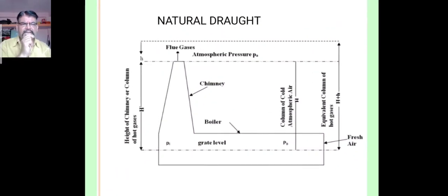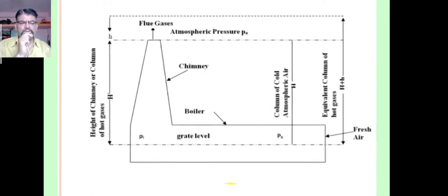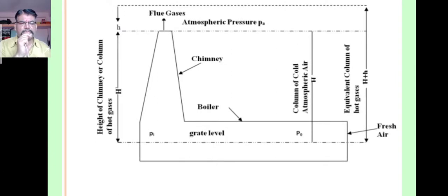So exactly, as I told you, the natural draught is obtained by use of a chimney. The chimney in a boiler installation performs one or more functions, we can say. It produces a draught whereby the air and the gas are forced through the fuel bed, furnace, boiler passes and the settings, and it carries the products of combustion to such a height before discharging them that they will not be objectionable or injurious to the surroundings.